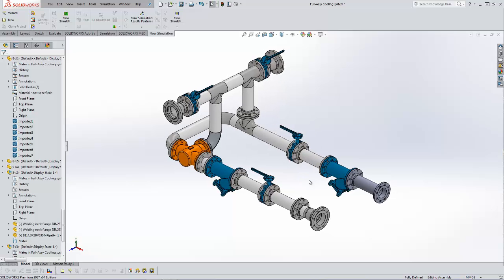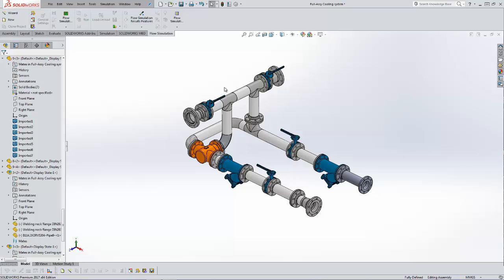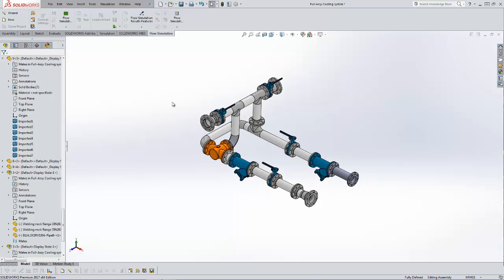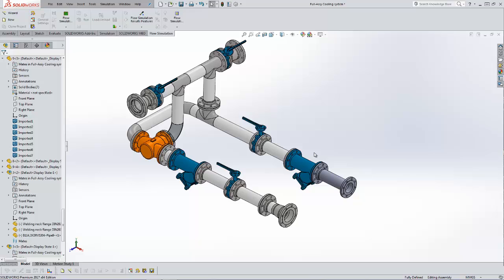As we all know, in ANSYS Fluent we need to create the fluid model instead of the solid model. SolidWorks is very useful software in modeling, and in this software we can also directly generate a fluid model. It means extracting the fluid model from the solid model. Let's take a look. First, how to extract the fluid model from the solid model. We do this.